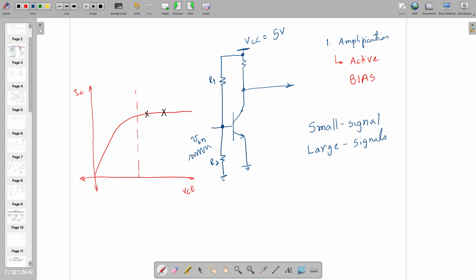But there is one small problem. Can you see a small problem? No, there is no capacitor right now. So my question is, what should you see here? VCC times R2 divided by R1 plus R2. Do you agree with this? Right? But are you going to see exactly that much voltage or something else?